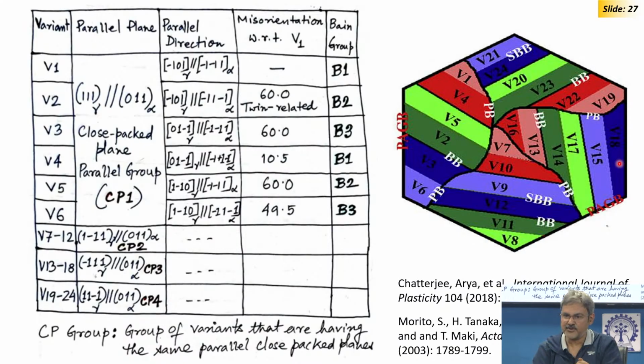We prefer high angle boundaries because they tend to deflect the crack. If a propagating crack is there, it is deflected at a high angle boundary. So, if you can create different high angle variants, then from that point of view it is better. For that, plastic deformation sometimes helps because you create strain, and this strain produces shear; slip is also involved because there is a slip plane and a slip direction. When the variants form, they tend to align their habit plane close to the slip plane. They tend to form their length along the slip direction. Likewise, if you apply plastic strain, variants may be favored.